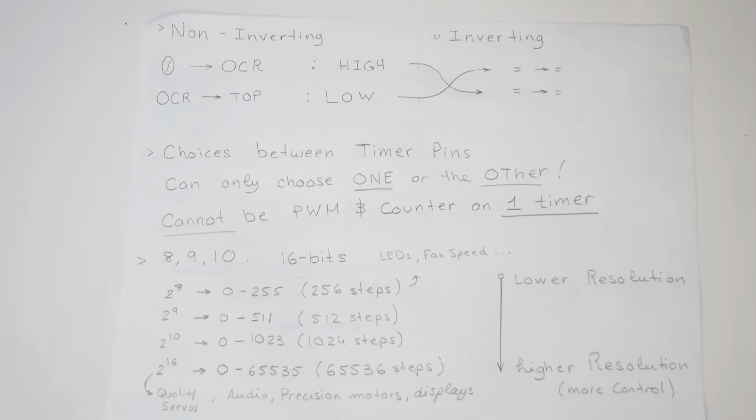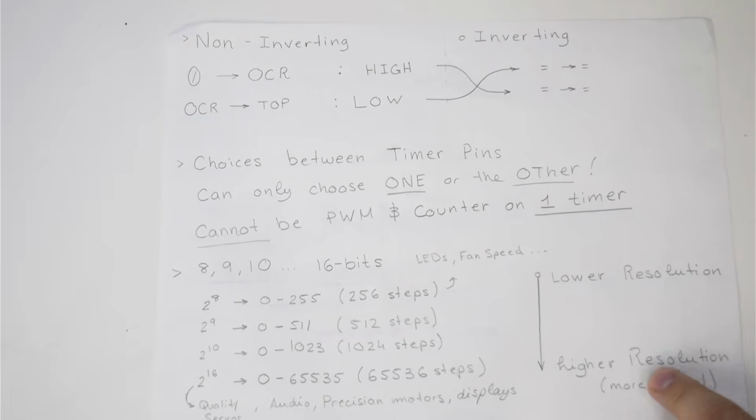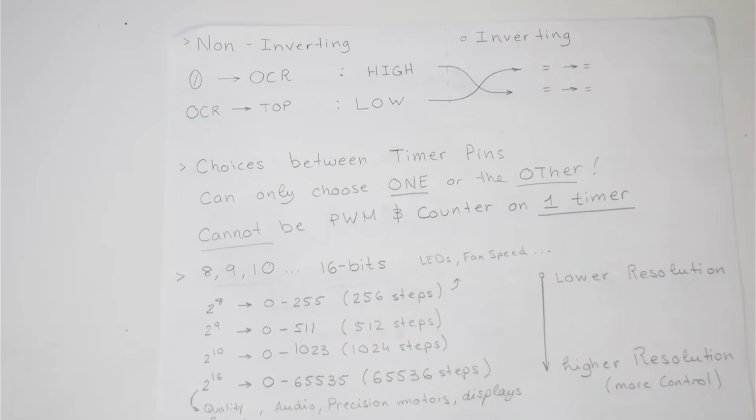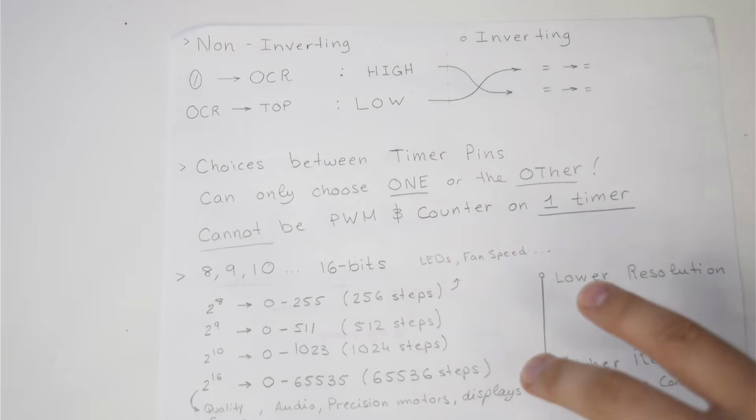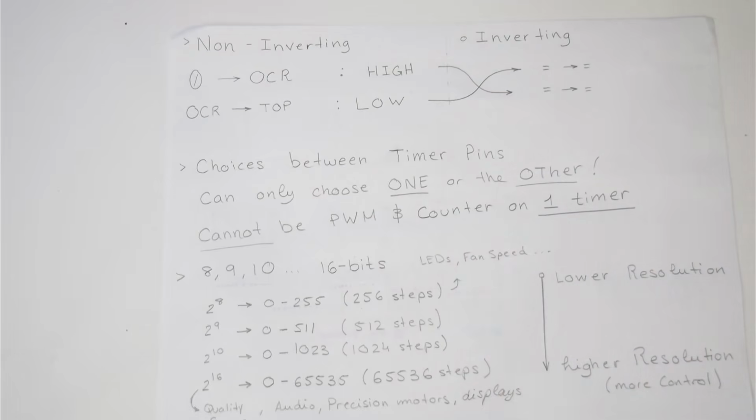That's it. Now, there's something very important when it comes to timers, and that's that depending on the timer, either 0, 1, or 2, you can set, let's say, timer 0 as PWM. That means that for timer 0, you have group A and group B, and both have to be PWM. You cannot have one as a timer or counter and the other as PWM. Remember how in the system setting we defined timer 0, I believe, as our counter.